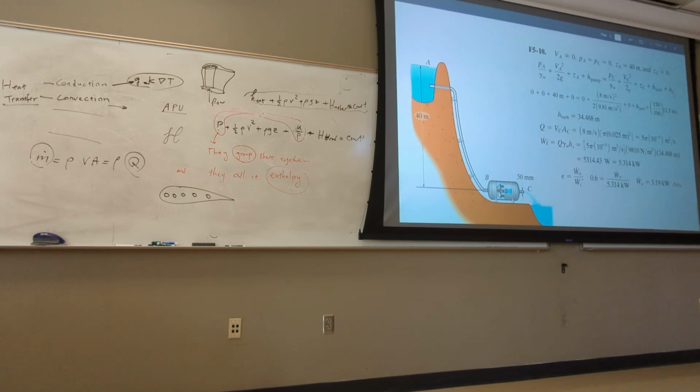And what about H loss? Head loss? You remember I just talked about it a few minutes ago? You said head loss per 100 meters is what? Then we have 150 meters. What do you do? 150 divided by 100 times the head loss. You see that's exactly what it does here, 1.5. So that 1.5 was head loss per 100 meters. If you have 150 meters, you do this simple proportion. You put it there, and you get the head of the turbine is this.